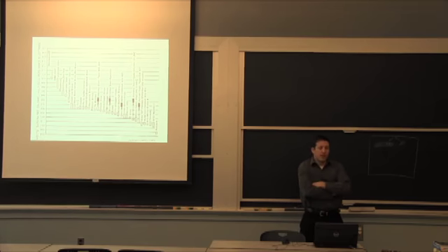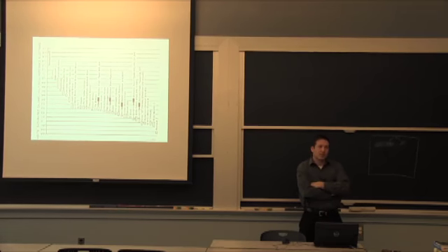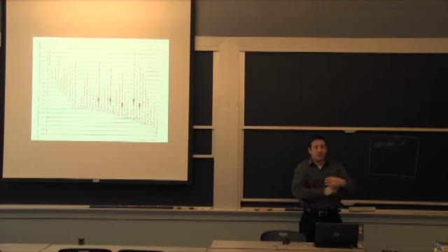Yeah, aluminum is not too sensitive to galling, but it essentially does have accelerated wear, whether it's adhesion or fretting, related to the two pieces having high friction together, and if they bond and then break between the surface oxide and the layer next to it, you get into a very accelerated mode of wear.